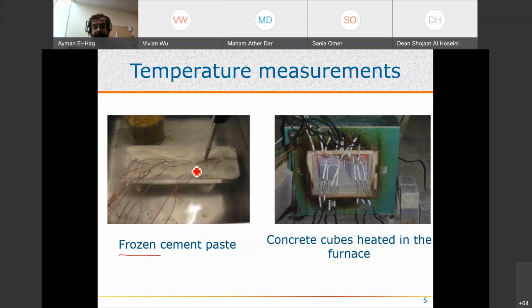But these thermocouples are connected here at certain points to monitor temperature, and at the other end there will be a monitoring system. There will be a voltmeter to measure the voltage that comes out of it. Remember that a temperature sensor, like any other sensor, changes a physical phenomenon into an electrical phenomenon.